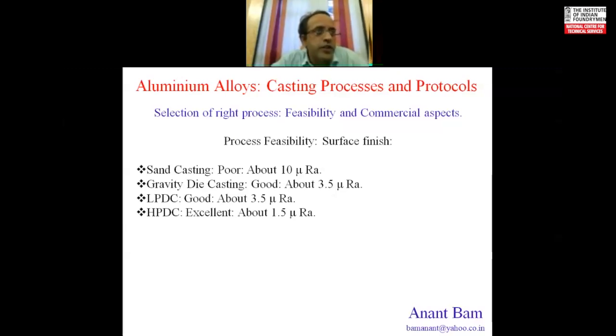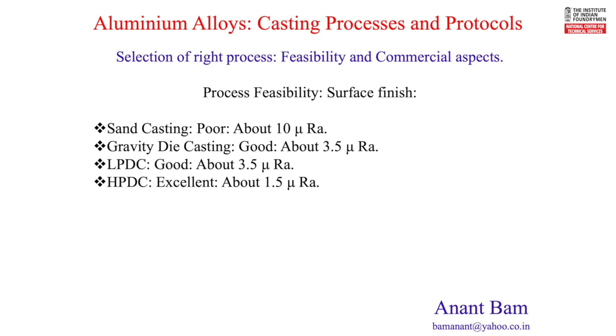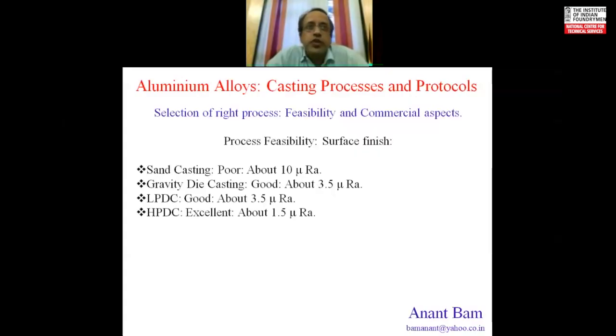The second function is that it has to impart surface finish. The third function of the emulsified lubricant is to provide cooling to the die surface. Since the majority of the water in the emulsion is evaporated during spraying itself, and all of it eventually evaporates before die closing, you are left with a thin film of the active ingredient, that is mineral oil or silicon oil.